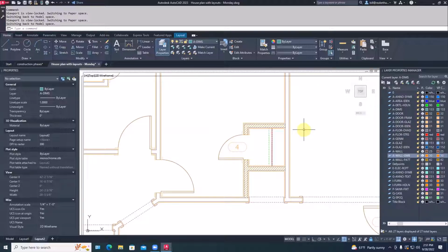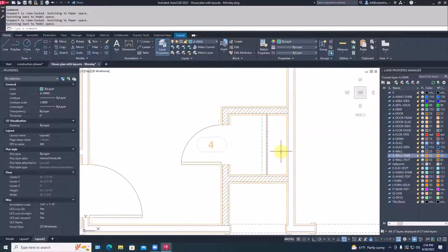So, telling a carpenter what to do. For something more specific, if we're looking at this closet up here, we have to tell the carpenter where to build things. You have a choice, and you would say in the general notes that you're going to give framing dimensions either from stud to stud or from finished face to finished face. Let's do finished face to finished face, and then he will have to subtract the half inch or add the half inch, whatever it is. So I want to measure from here to here, and then from here down to there.